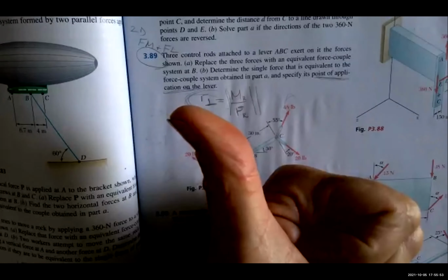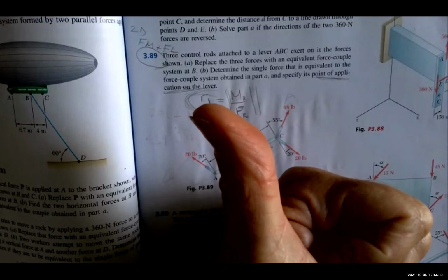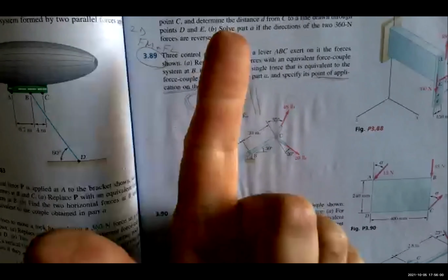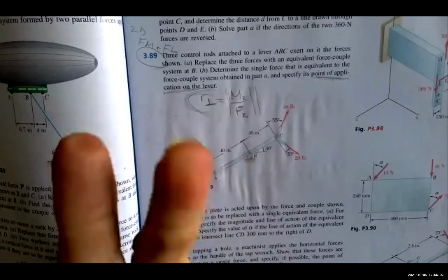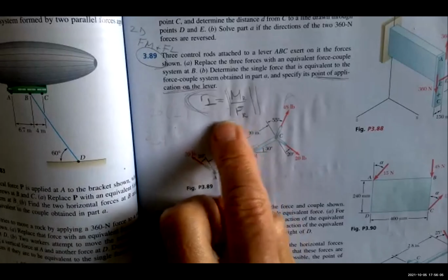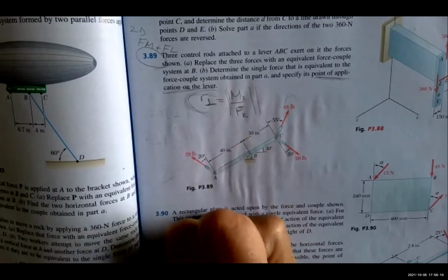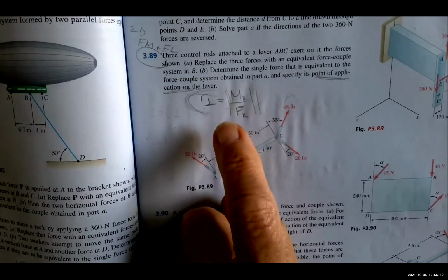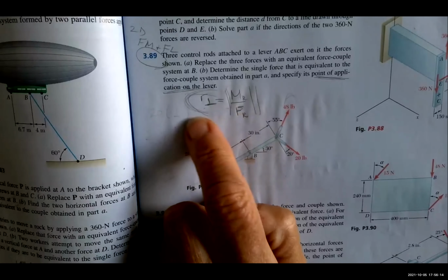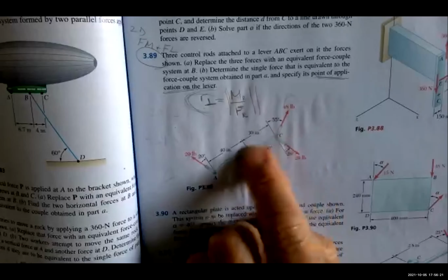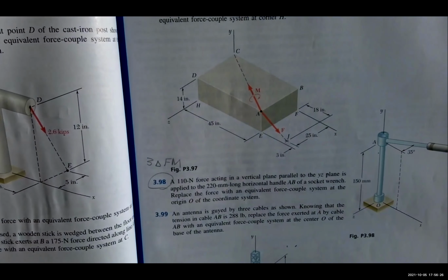So force location problem, first you would find the resultant force, the resultant moment, then you would find the perpendicular distance. Right, and then the fourth step is to draw the location, one force at that distance. Right. Great. What's the next problem?